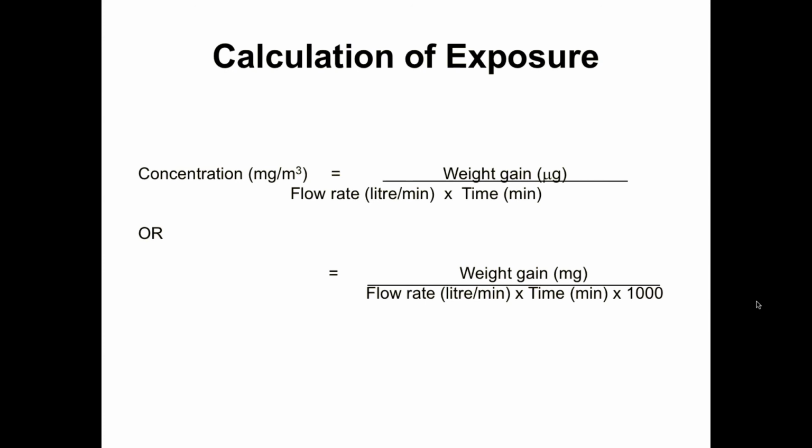Now the weight gain, though, let's think. The flow rate seems pretty straightforward, you're going to use the average flow rate, the average of before and after, times the amount of time that you sample. Pretty straightforward. Well, what about the weight gain? There are things that could happen that would compromise your estimate of what the actual weight gain is.